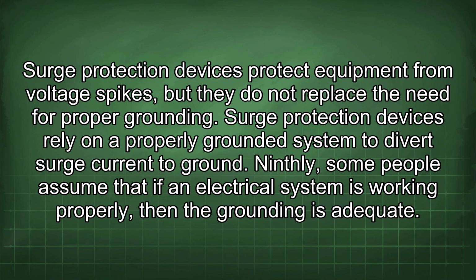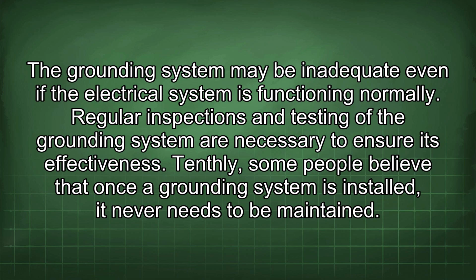Ninthly, some people assume that if an electrical system is working properly, then the grounding is adequate. The grounding system may be inadequate even if the electrical system is functioning normally. Regular inspections and testing of the grounding system are necessary to ensure its effectiveness.